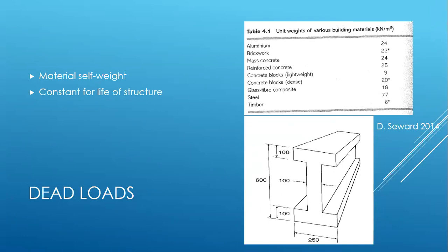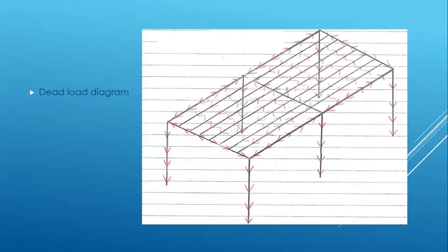As the dead load was not known at the time of selecting structural members, the assignment activity required a member to be chosen, its dead weight added to the calculation, and a determination made as to its adequacy. This led to members being increased in size after load calculations were applied and it was determined that the member was undersized, as well as members being reduced in size where it was determined a lesser member could perform.